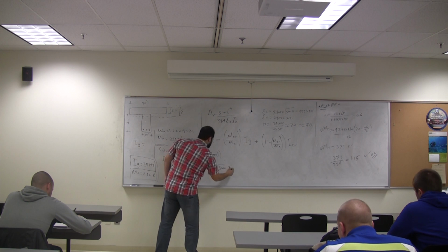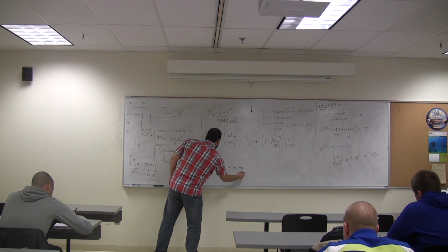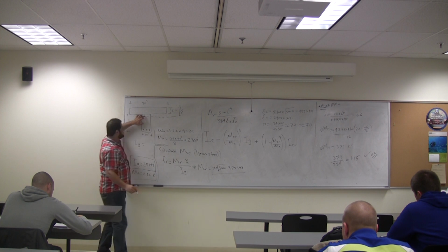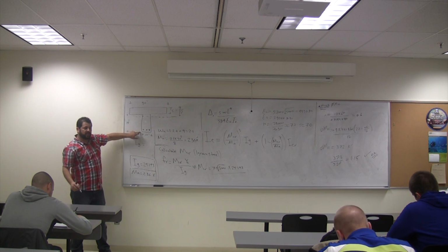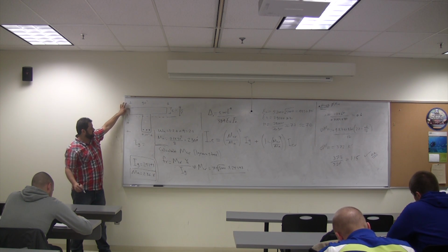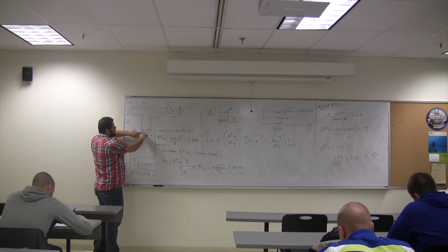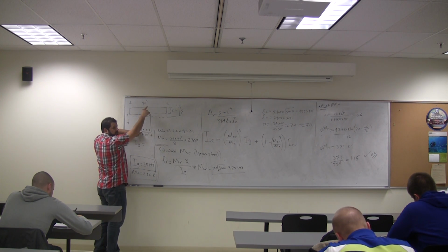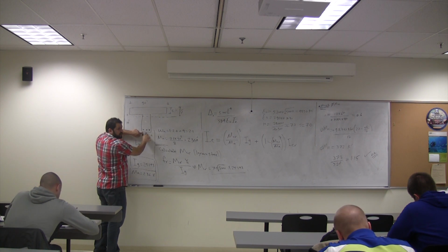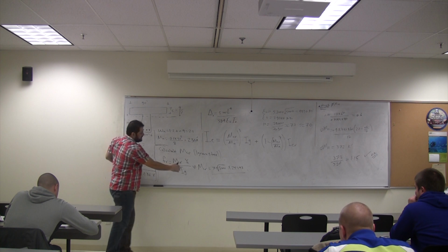Here we have 25,143. What's Y to the tension side? YT. What's Y? 18. It's 6 from top. This is the location of the tension. This is where we calculate FR, not at the top. This is where the crack will start. That's FR. So 18.